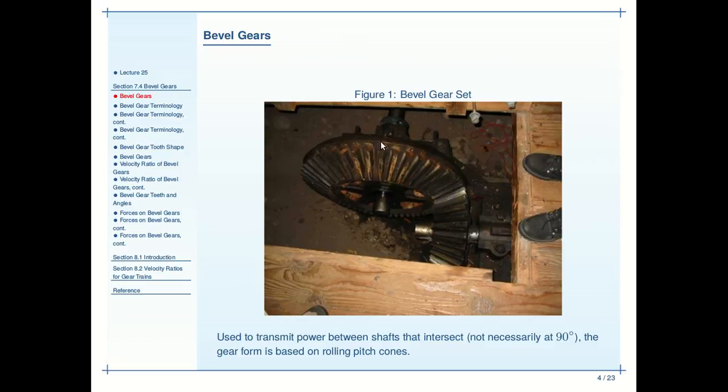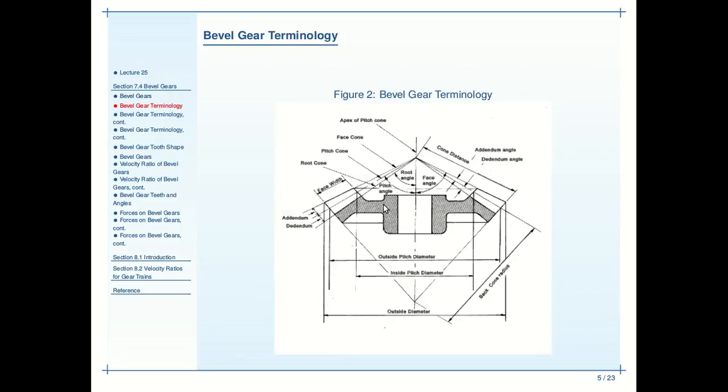So this is the maximum size of an involute tooth profile, and it scales down to its minimum size at the innermost portion of the tooth. Obviously, if you continue that scaling all the way out to that theoretical apex point here, the tooth will get infinitesimal in cross-section.